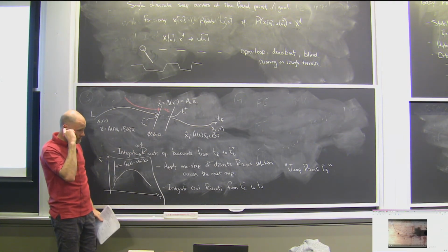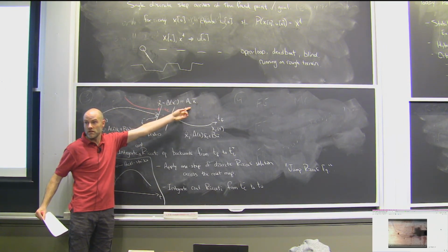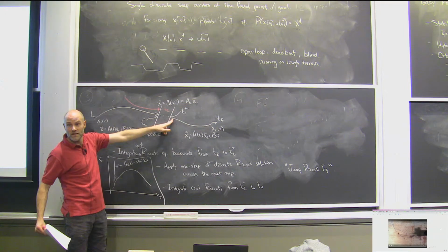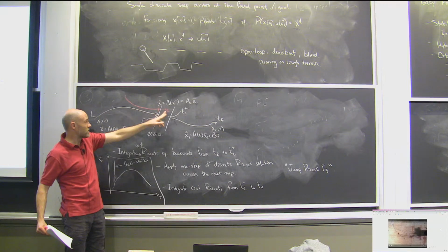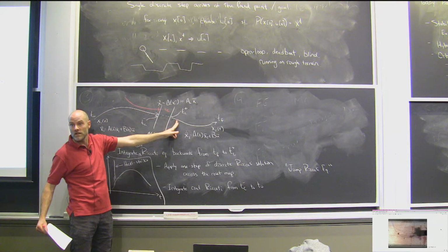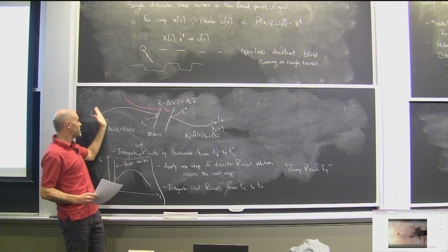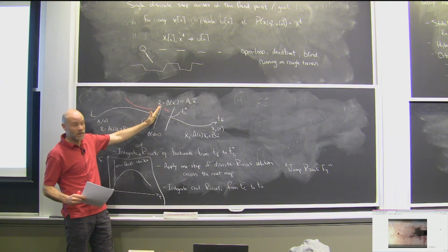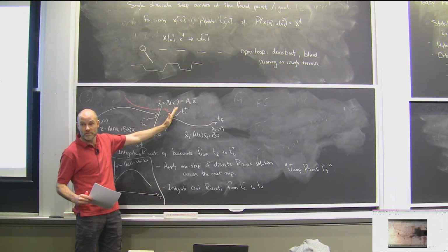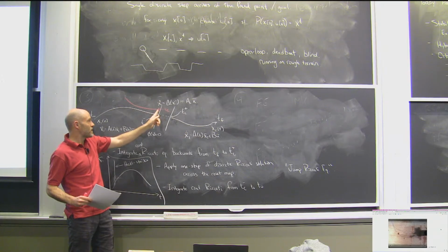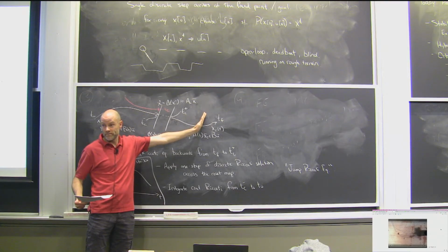Okay? Which means that the linearization that I use of that reset map is going to be a little off, potentially. For this cycle, immediately, it could be doing the very wrong thing until things catch up. Did I say that well enough? If I'm clocking my linearization only off of time, the linearization I'm using for control, and that linearization changes discontinuously, then if I'm on the wrong side of the guard using a different linearization, then my linearization is not valid.